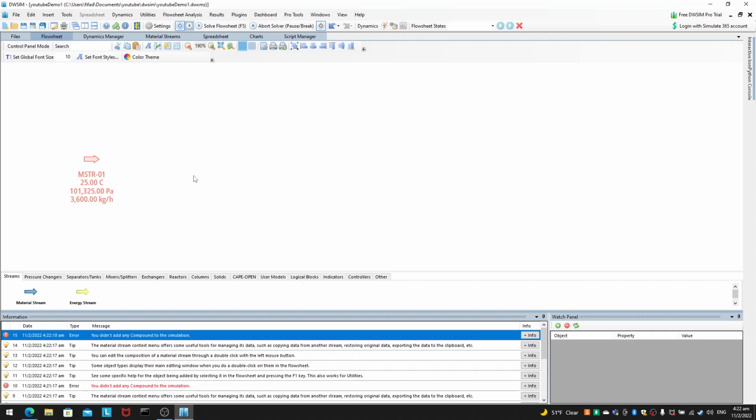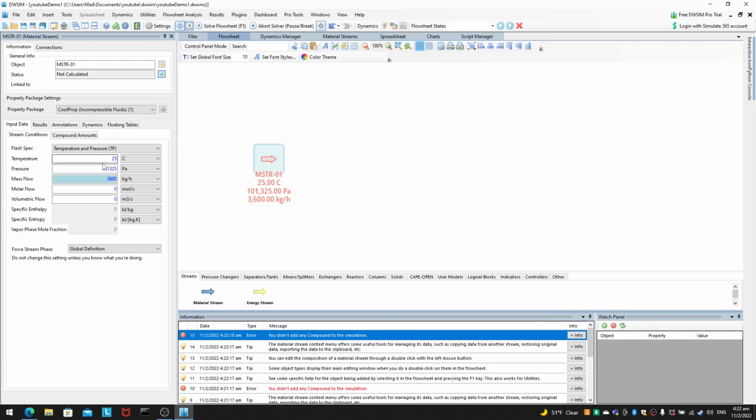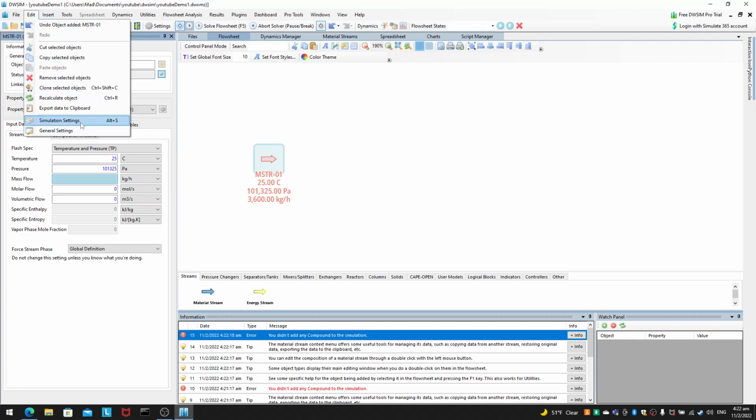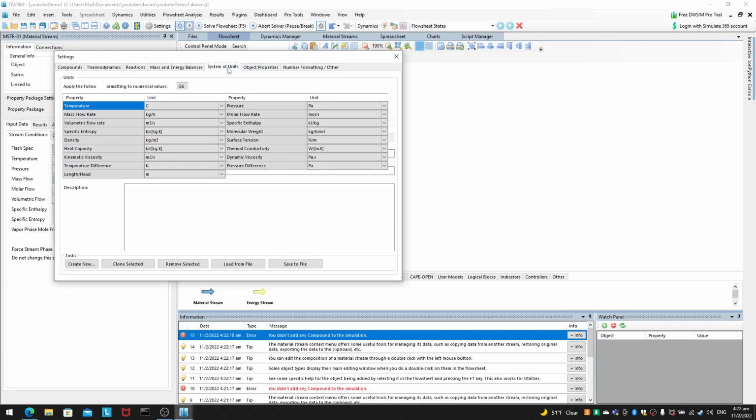So it's going to be an isothermal case, and I don't want so much flow rate. That seems ridiculously crazy. Maybe I'll just put 0.04 or 0.05 kg per hour. Maybe I'd like to change the units again. I don't like kg per hour.